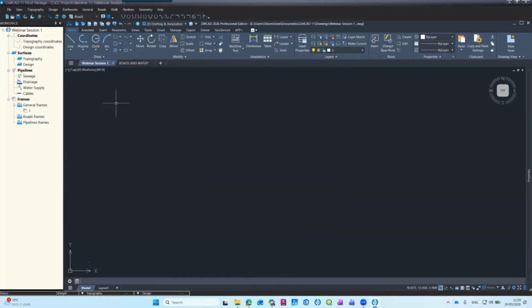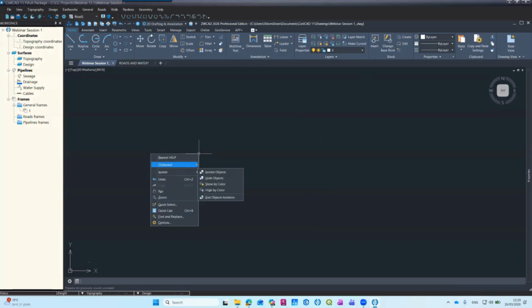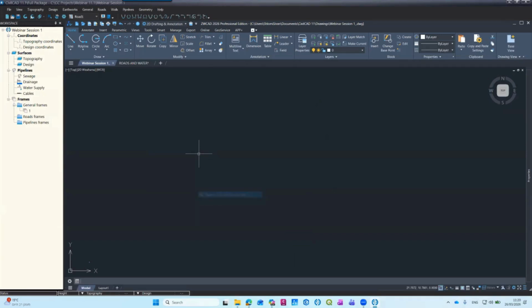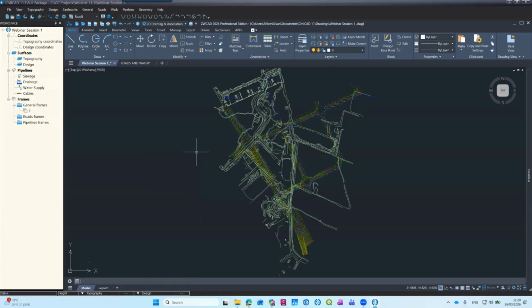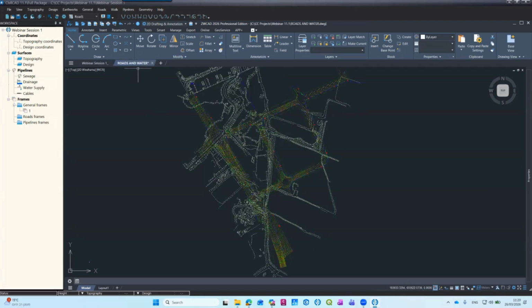Go to my own DWG, which is associated with my project, and right-click, clipboard to regional coordinates, and that's it. Okay, now I've put it inside. Of course, I can use external reference, block reference, but this is the easiest way. So I just open a DWG, copy everything, inside, and now it's part of my project.